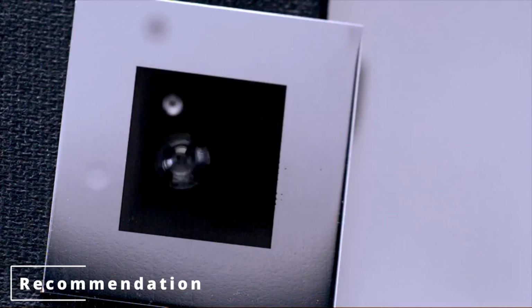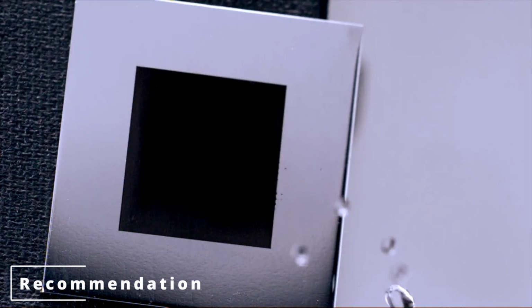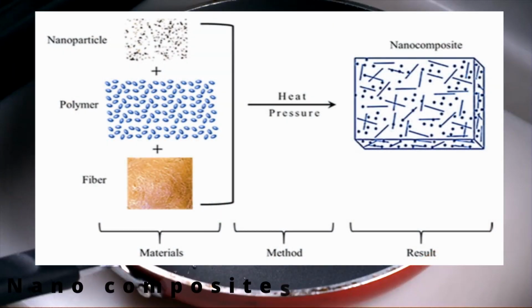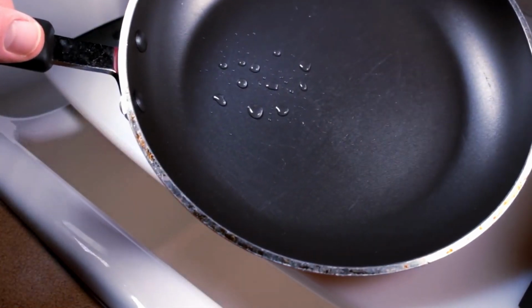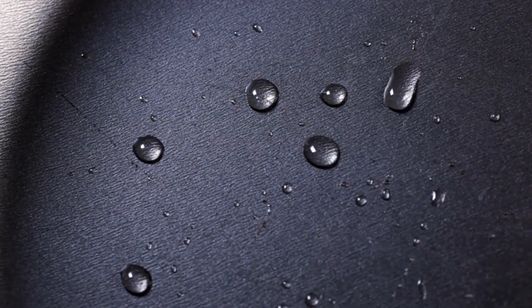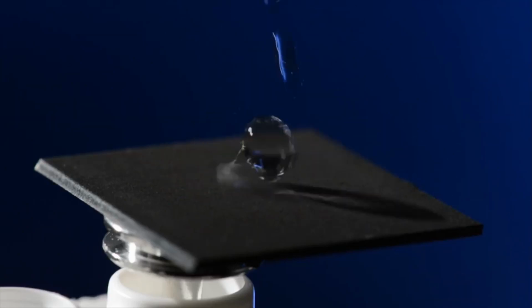Hence, in the manufacturing process of the insulators, these results can be considered to optimize the model. Introduction of nanoparticles in the mixture to maintain the surface tension of the insulator will be a feasible way to achieve this. This has to be studied and analyzed in detail. Super hydrophobic silicone rubber materials are preferred in the industry owing to their abilities to roll water droplets and self-clean. These super hydrophobic insulators are designed to accommodate water droplets having contact angles more than 150 degrees.